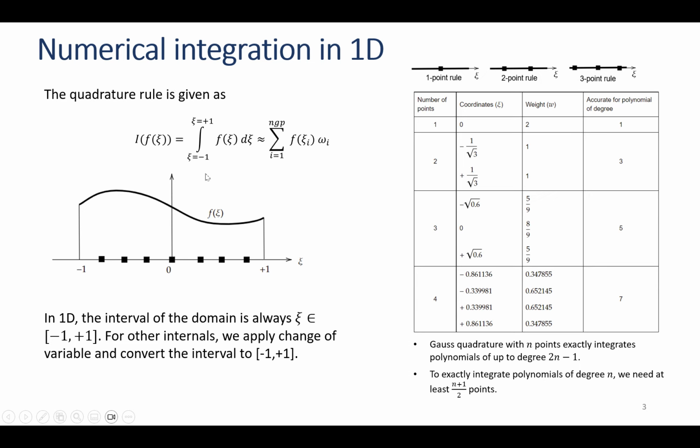We can as well derive the numerical integration schemes for different limits, but this is what we use. This is the standard that we use. So in the xi coordinate system, the integral is from -1 to +1, and we evaluate the integral of this function f with limits from -1 to +1.